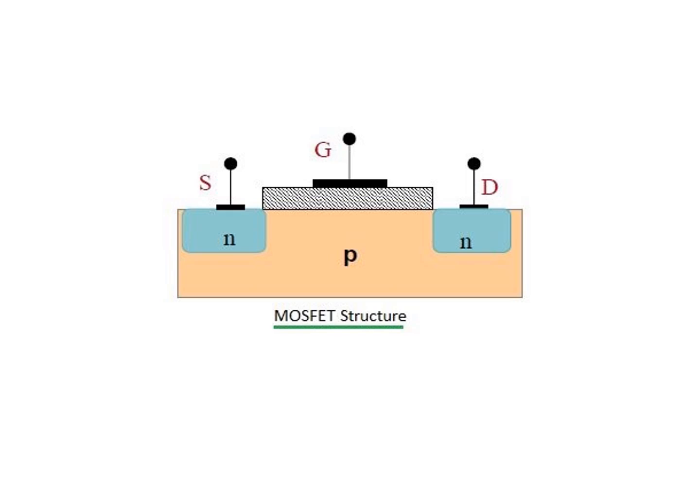So now the structure of MOSFET. MOSFET is a four-terminal device with source, drain, gate, and the body terminals. The body is frequently connected to the source terminal, reducing the terminals to three. It works by varying the width of the channel along which charge carriers flow, which are mainly electrons or holes. The charge carriers enter the channel at the source and exit via the drain.